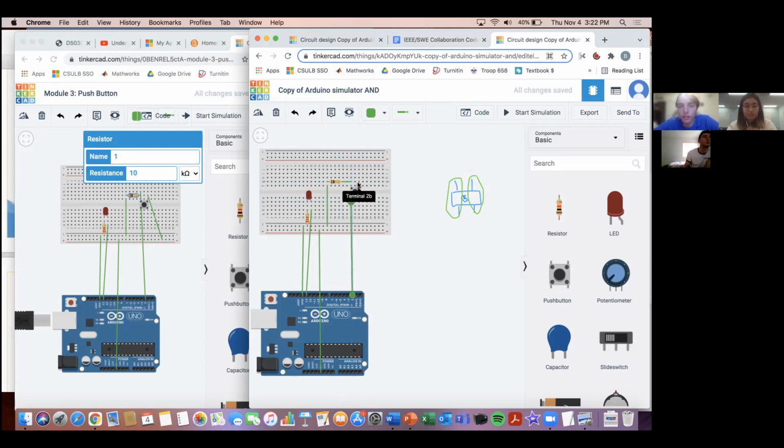And then you're probably wondering, why do I need to hook this one up to the voltage? Basically, I need to hook this one up because we have to make sure that when you push the button, it can toggle between 0 and 1. And that might cause an error when read, because when you push it, it's going between 0 and 1. It's not staying at a consistent value. So when we hook it up to the voltage source, it's going to keep it at the high value for what we want, so it doesn't switch in between and make all this weird output.